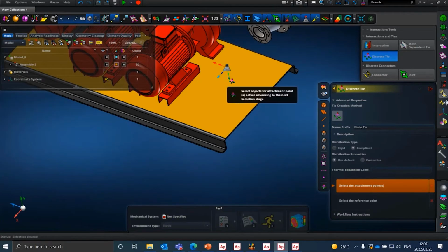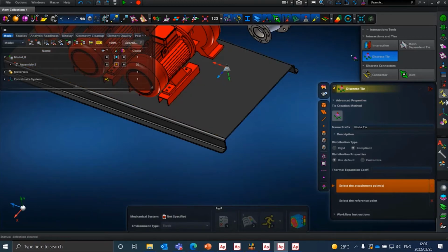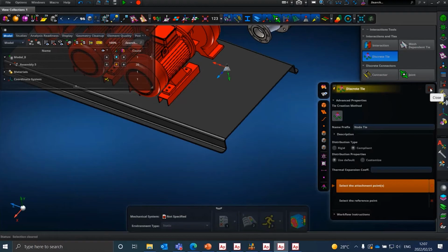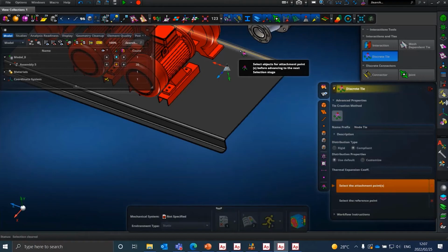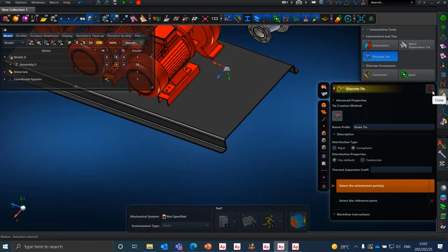The other thing that I should just mention again as well, it can only use the data that you provided. So if the center of mass is not at the correct location, that is possible because it only uses the geometry itself to determine that location. And if your CAD is not an accurate representation of what is actually being modeled, or what is actually in reality, then obviously your mass and your center of gravity will be in the wrong location.